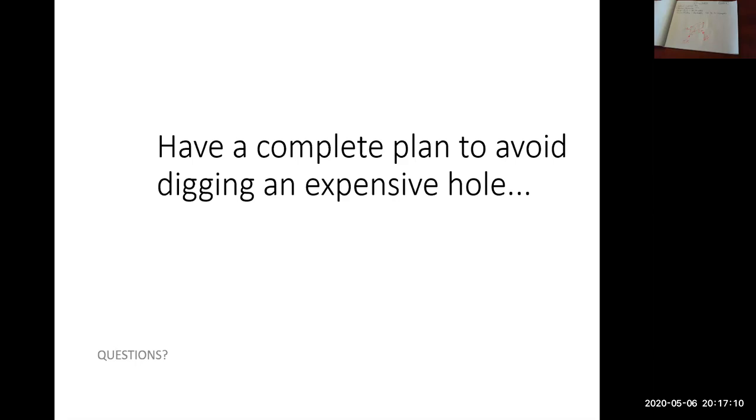So using your pencil and drawing all over your tender drawings is a good idea. You never have to give those back, they're yours. So draw all over them, make notes, use colors, anything to help you understand what's going on the drawings. So some other notes that I have here. So do required cut slopes fit? So that goes to my oil interceptor example with the building that's close by.